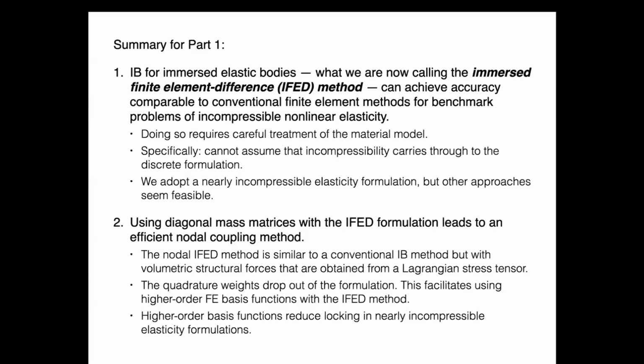To make these methods fast, it's worth going to the trouble to figure out how to make all the coupling nodal, so that you are only coupling from the finite element structure nodes to the background grid and back. We originally were doing this with coupling that was using Gauss rules, and computations were, I think, maybe 10 times slower, which was not something that we could afford to do for these large scale models. Okay.